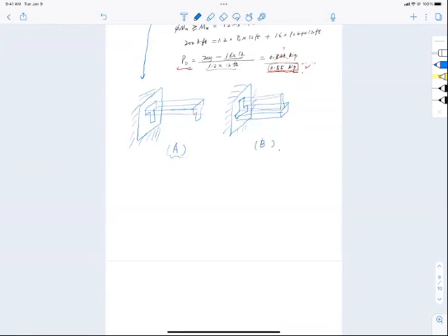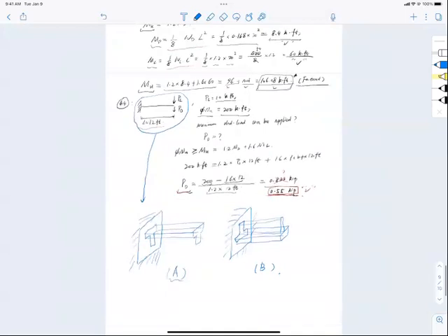I'm going to pick my next victim. So knowing that my condition is a cantilever, and my load is at the end of it and pushing downwards, let me spell it out for you even better. That is to say that my bending moment here is negative.